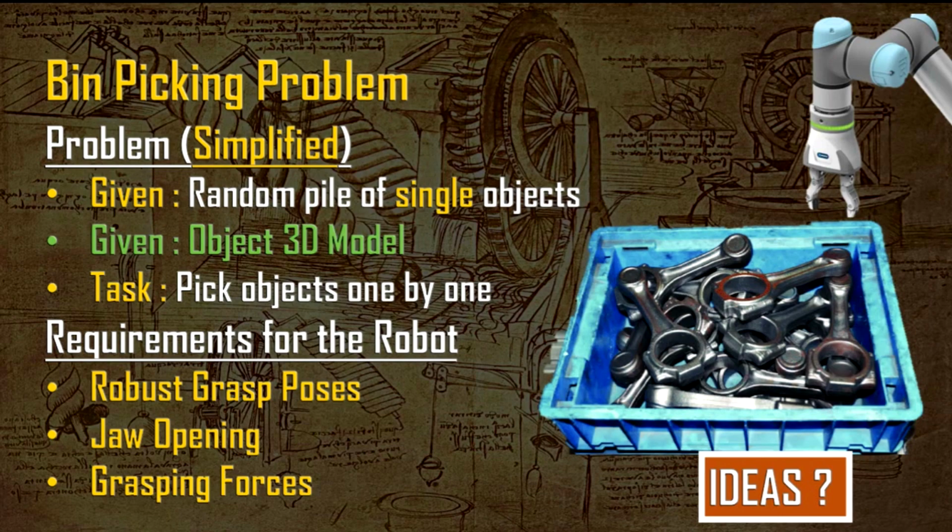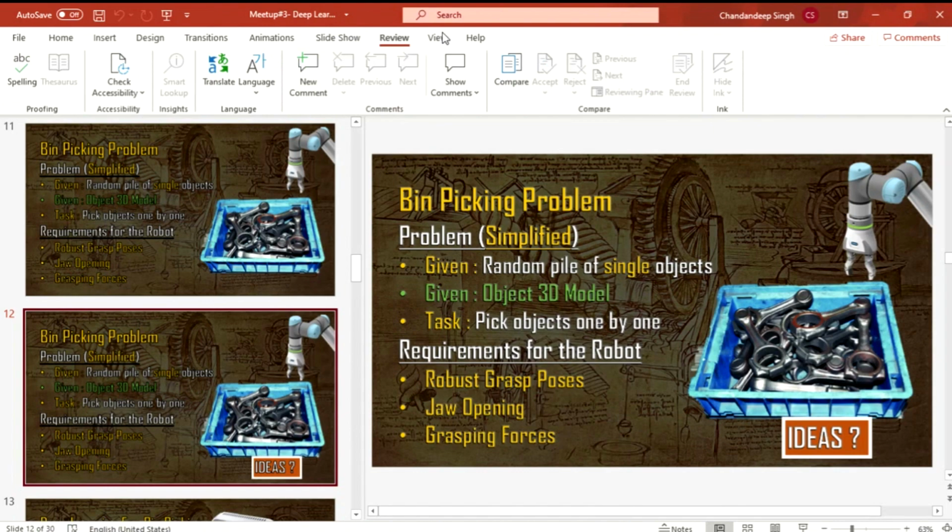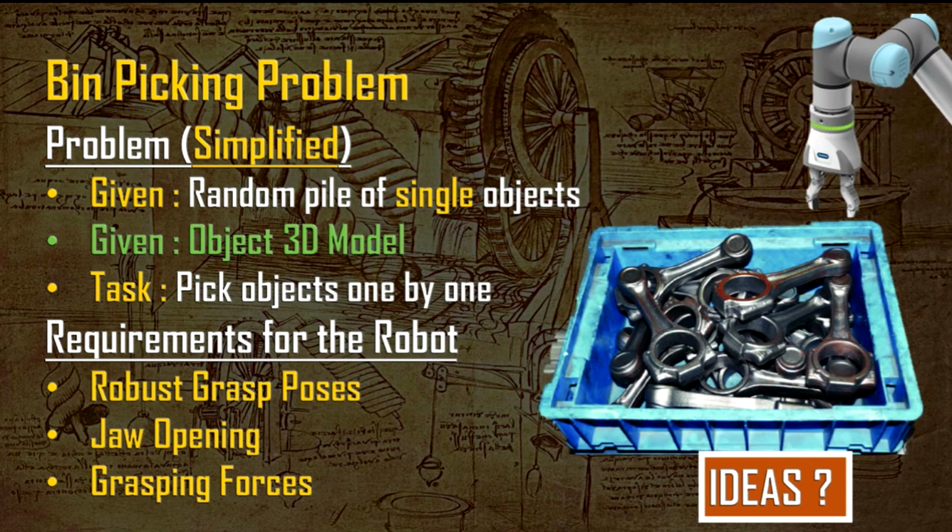This is how it works. You will have a fixed location of the camera in your cell, and you would have already fed the camera location into the robotic system. There will be a transformation from the end effector to the camera, and from the camera to the identified object. The transformation matrices will be calculated, and the complete forward kinematics will be calculated. Based on that, the object location in the 3D world would be identified from the camera and given to the robotic system, and the transformation from the object location to the end effector position would be calculated on the fly. Then the robot will be able to pick up the objects as you go on picking them, even if you go down. I think Vamsi answered your question, right?